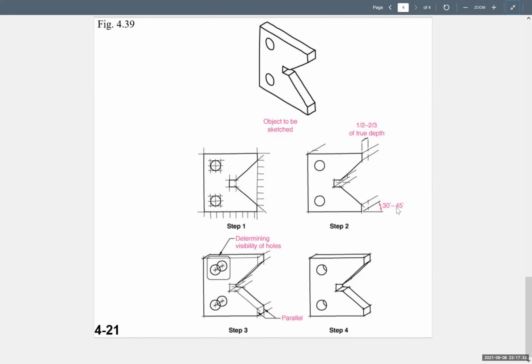They're showing you a range of 30 to 45 because there are other ways to draw, like architects might draw something different. But for obliques, we know it's 45 degrees. So at a 45-degree angle, I am going to draw in the line that shows all the depths and the depth here. And then I'm starting to connect the lines. In a way, I'm drawing the front face now on the back face, and then I connect the lines. It is intense. This is a new thing for many of you.